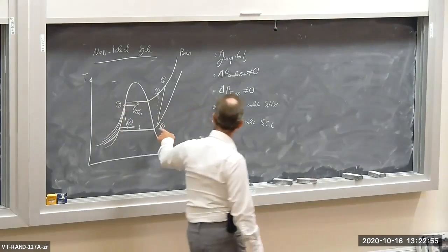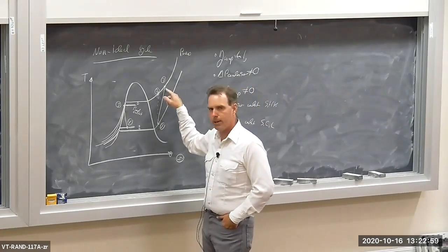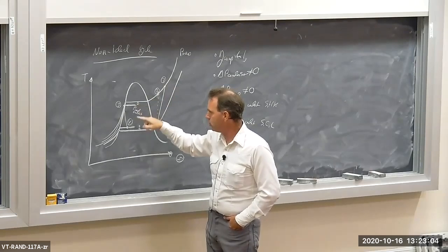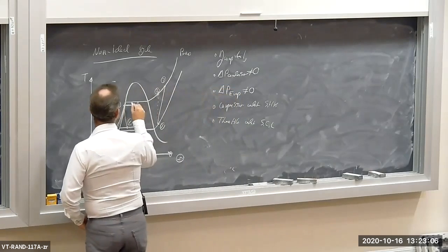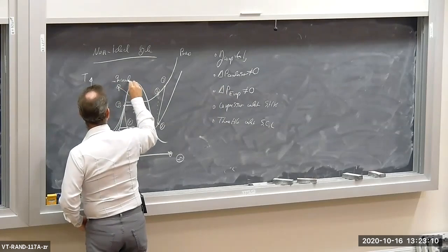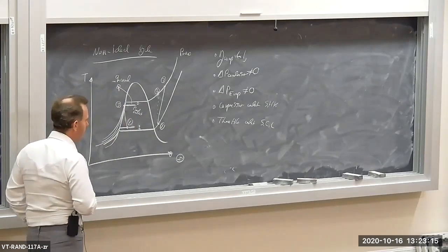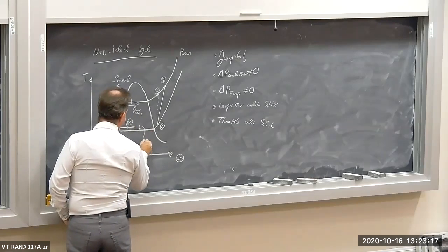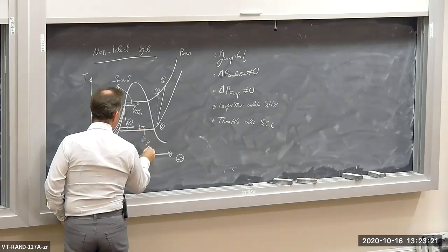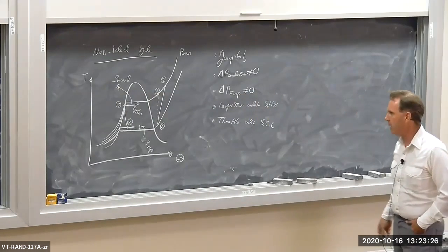We could have a superheated vapor at the inlet state for the compressor. We could have non-isentropic operation for the compressor due to irreversibility. We could have a pressure drop in the condenser. We could have a supercooled liquid for the inlet state for the throttle, and we could have a pressure drop across the evaporator. These are all things that are deviation away from ideal behavior, okay?